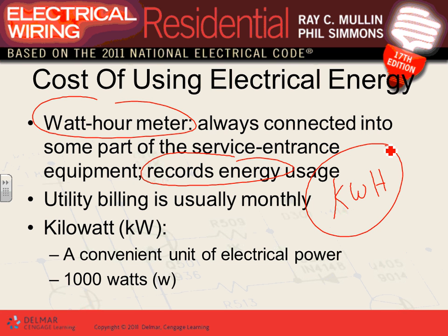You consume kilowatt-hours. What's the kilowatt? It's the power. What's the hour? If you multiply the power by the time, it gets you energy. That's how much energy you will be consuming at your house. 500 kilowatt-hours or 1,000 or 2,000 kilowatt-hours a month. And every kilowatt-hour, what do we pay here? 9 cents. Multiply this by 9 cents, and that will get you how much your monthly bill would be, plus other fees that they add to it, and maintenance and what's not.